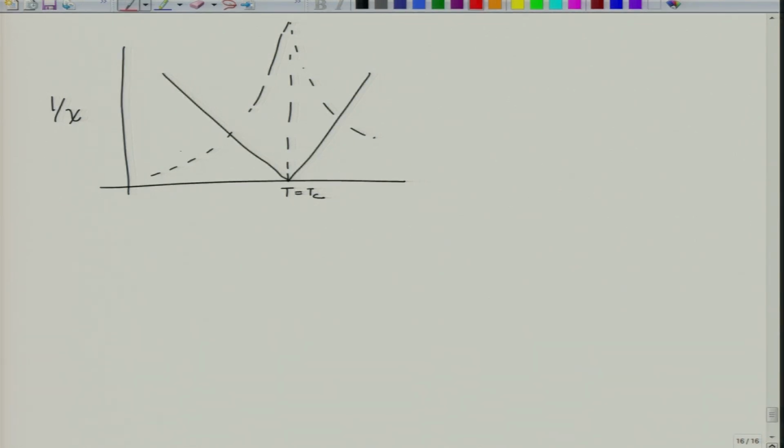So when you measure the dielectric constant, the dielectric constant goes like this, right. So this is, let us say, the dielectric constant, and the dielectric constant is nothing but 1 plus chi, right. So this tends to diverge at T is equal to Tc, that is very large susceptibility, or 1 over chi will show a dip. At this point we basically have to ignore all other contributions such as electronic and ionic contributions as well as interfacial polarization. We assume that alpha d is much higher than alpha e plus alpha i plus whatever else, alpha interfacial and so on and so forth.